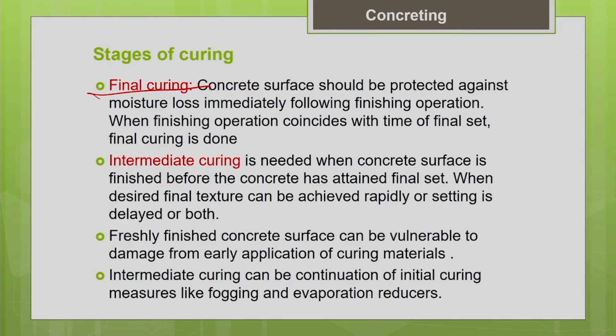So, the ideal case is your final finishing will coincide with the final setting time. Once the concrete has attained the final set, you can easily apply the water for the final curing. There the concrete will not get damaged because of application of the water. So, that is the right time to apply. After the final finishing, after the final setting of your concrete, you can apply the water to do the final curing. But in some cases what happens is your final finishing will be completed even before the final setting of the concrete. So, before the concrete attains its final set itself, your final finishing will be completed.